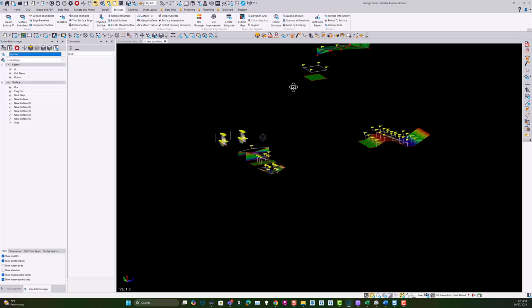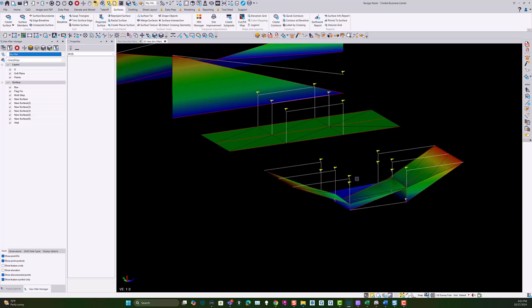Let's take a look at this in 3D and just take a look at the reasons why you get flags in a model. If you're looking at cross-section work, you'll often get vertical walls in cross-sections. This is an example of a cutting, and in this case you've got multiple points in the verticals here, sometimes 2 points, one at the top and one at the bottom, sometimes a point in the middle. It's all very common in surfaces, and you can fix these by moving these nodes at the top of the walls backwards and deleting the extra nodes in here just to give yourself slightly off vertical.